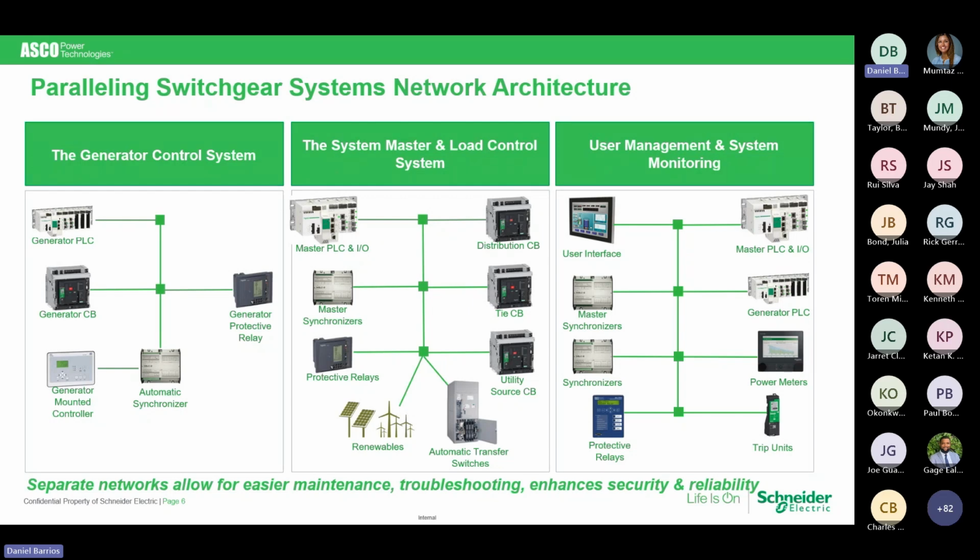When you are retrofitting a set of generator sets or a system that has older generator sets, it is not uncommon that we're going to reach out to you and ask, what is the vintage? What type of controller is on there? And also, you may need to update the controller on existing generators. You may need to update the voltage regulator or such, depending on what type of system you have.